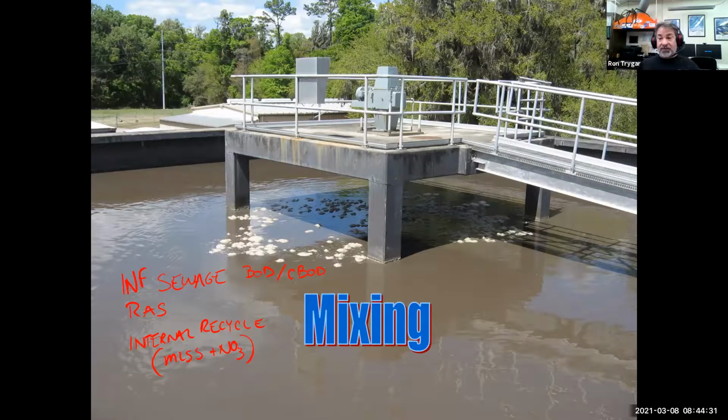And in some cases, if this anoxic basin is further downstream, then we may not have enough of the carbon coming in, and we may have to supplement that to make that actually work. And that's kind of more common in the 4-stage Bardenpho type of situations, the AO processes, the A squared O processes, or say other BNR facilities that may lack enough carbon downstream. So we may find that we have to produce or give them some extra carbon, actually purchase it rather.